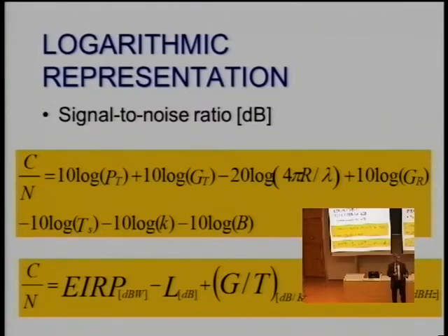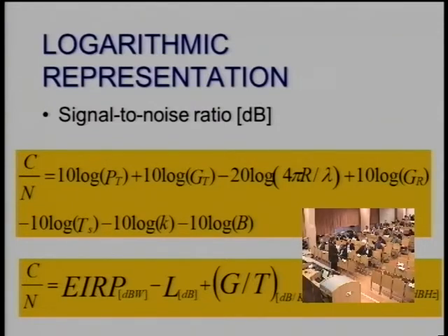If there is additional attenuation due to fading, a weather effect, it's raining heavily, then that's there. We can't do anything against physics, but we can take some countermeasures. With adaptive transmission, a very simple way would be to reduce the bandwidth, and this way I improve the signal-to-noise ratio again. Of course, the other possibility would be to increase the power. Uplink power control is a very traditional way of doing that. And again, I can get to a healthy link budget.